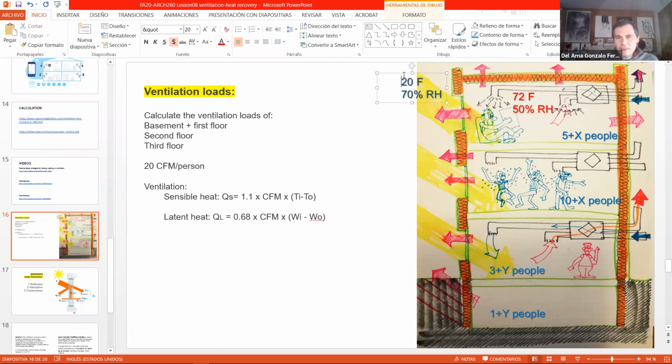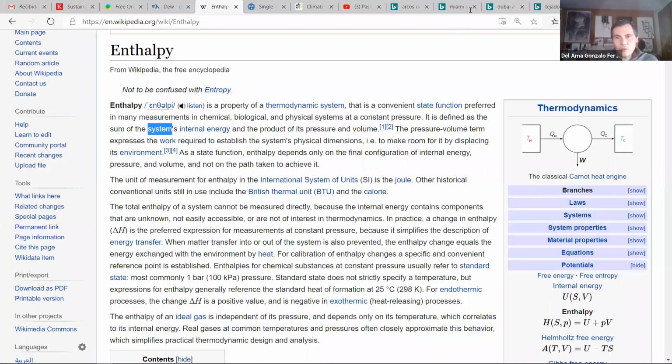Where do we get these values from? I mean, for the indoor values, everything between 40 and 55 relative humidity and 68 and 74 Fahrenheit is fine. It can be 72 and 50, or 70 and 48, or 71 and 52, whatever. What about outdoors? Well, outdoor conditions depend on where we are. And I'm sure you can Google.